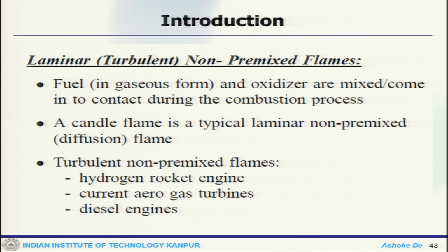Now, what happens when you come down to a non-premix system? As the name suggests, the reactants like your fuel and oxidizer are not mixed a priori before the combustion takes place. The fuel and the oxidizer are mixed when they come in contact during the combustion process.